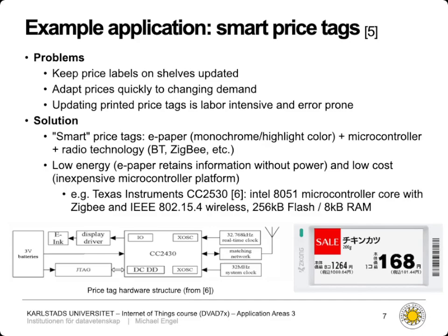over a very simple interface, like for example SPI, because you don't have to update that label quickly. It can take a second or two to just update that information. Nobody cares. You're not going to play videos on these. Though there are relatively fast e-paper displays nowadays available, of course.